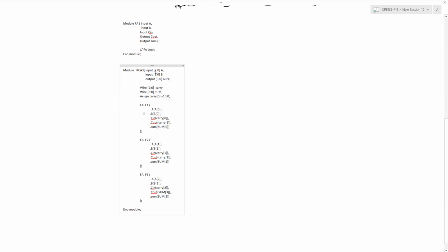And so now we have our ripple carry adder, which we've created with a structural model. Now, an important thing to note here: each of these components we've instantiated, these full adders in this case, can happen in any order. All of these components, as well as the continuous signal assignments, such as this one, all happen in parallel. So the order can change, and I'm going to get the exact same design.